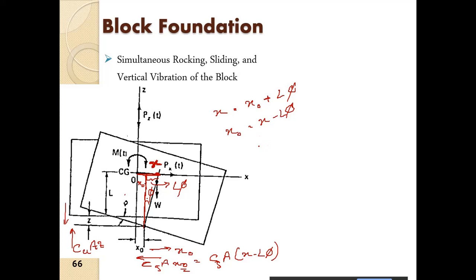Now let us consider the moments. The moments will have to be considered about the CG of the block foundation, because we have to consider the rotational equilibrium. So first of all, let us consider this force. This force is uniformly distributed and it will be acting through the CG.